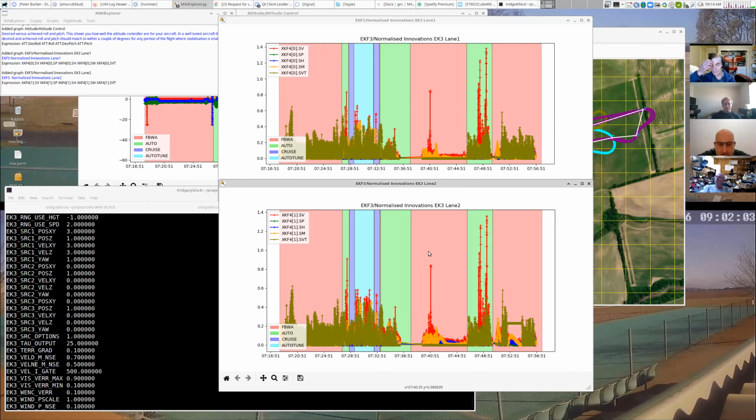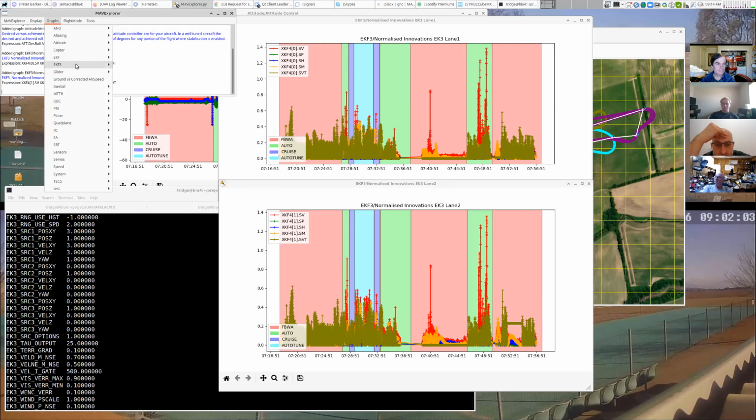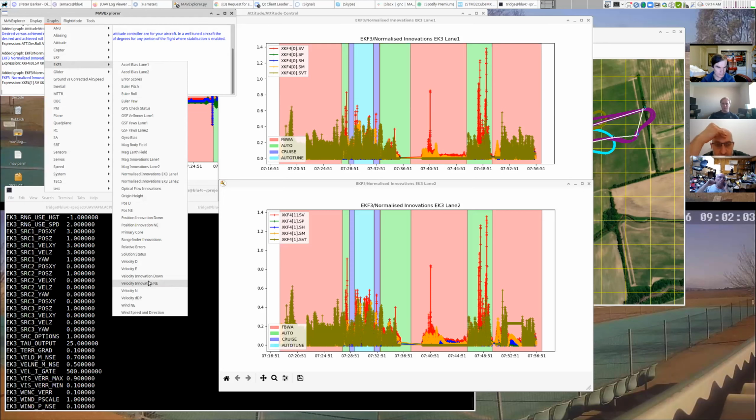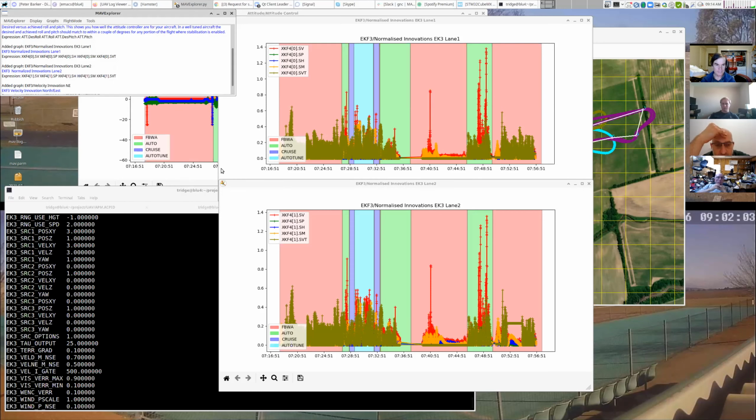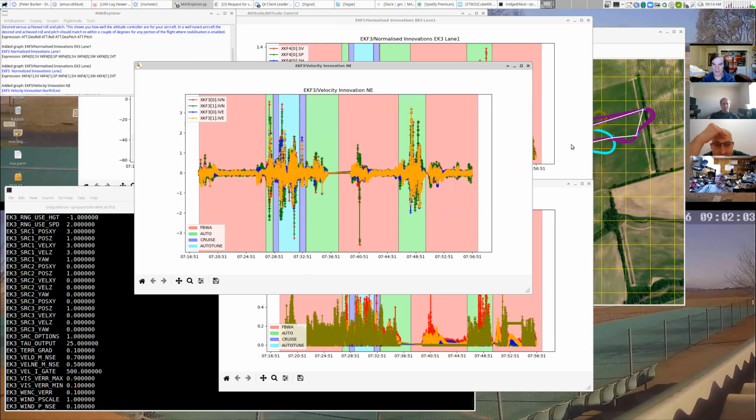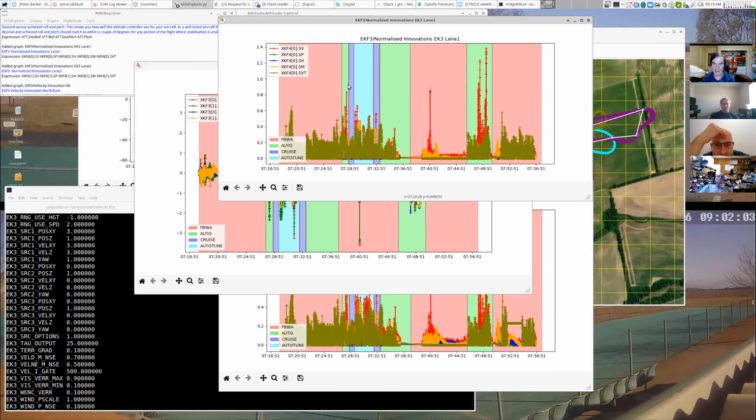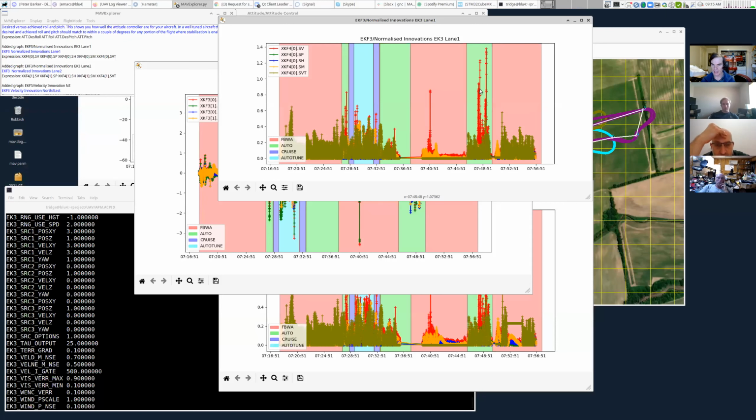Thanks, Paul. And if we have a look at that log, because it's just the velocities where you're seeing the larger innovations, what I do typically next is have a look at the GPS receiver's reported velocity accuracy to see what's happening. And on this flight, that's a very interesting plot. All right, so let's have a look. So as Paul said, these scaled innovations tell you how close you are to rejecting. And we see it here, it's actually rejecting the velocity a little bit.